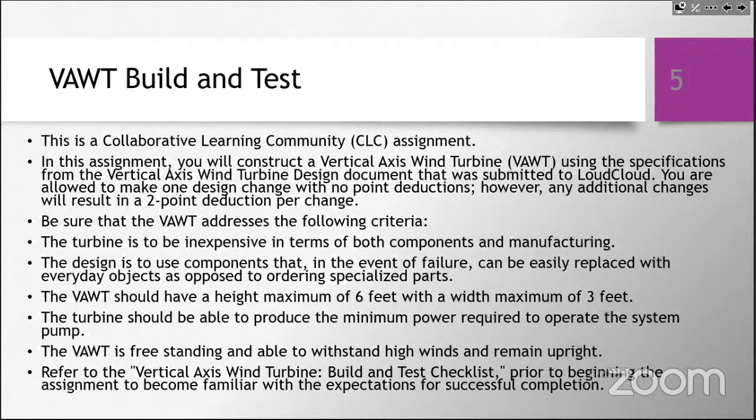Typically when you design things that have holes, you want to undersize them in 3D printing because you can always ream it out, but you can never put the material back in. So undersized is probably a little bit better than oversized, because if you did mess up, you're at least giving yourself a fudge factor in the right direction.